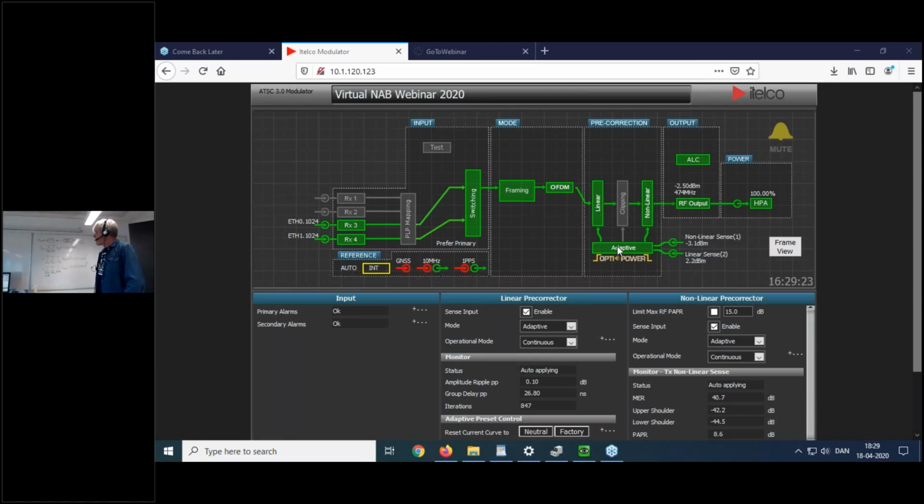The paradigm changes a little bit when the digital is added to the FM, because the FM you can often do in a class F transmitter, because you can drive it almost to saturation and then filter away the harmonics. But as soon as you have OFDM signals, then you have a requirement of linearity.